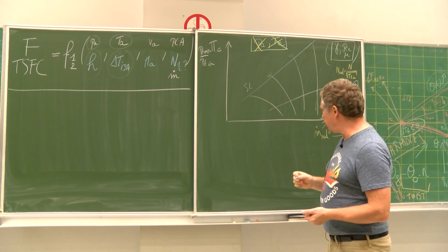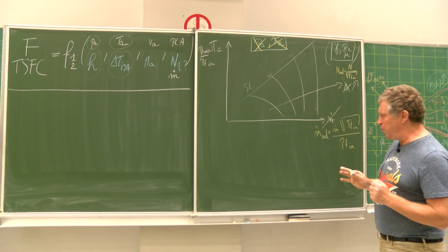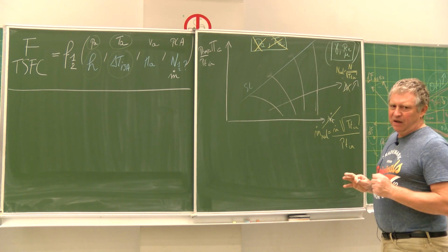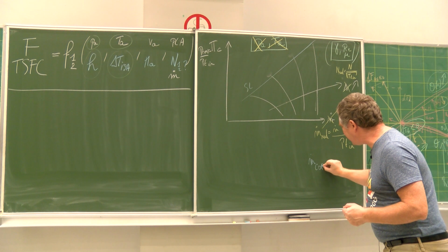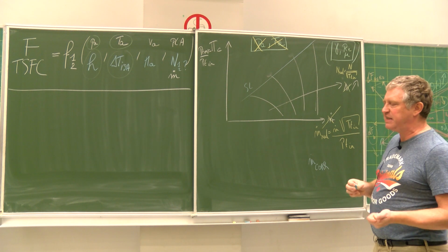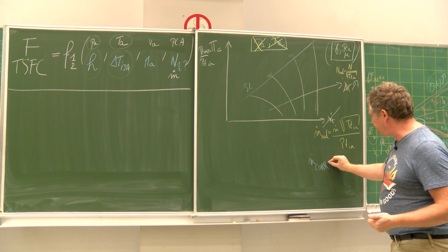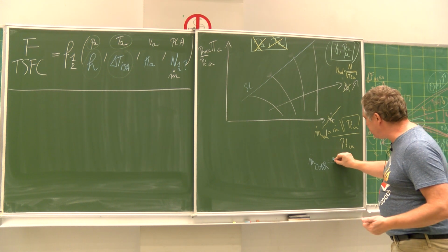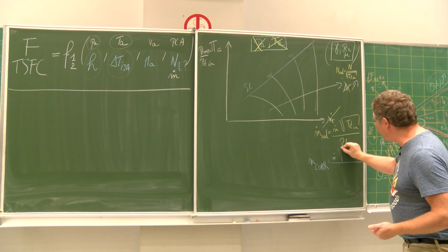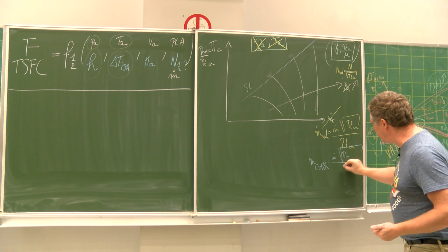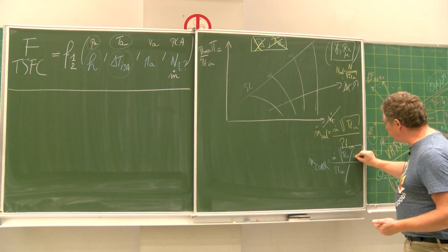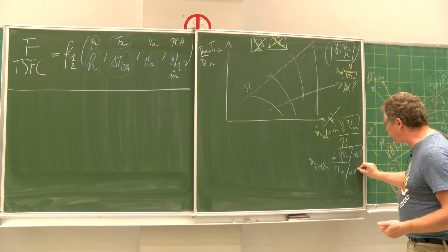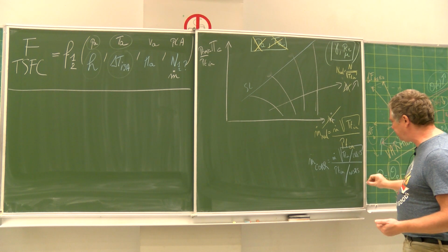I remind you also that we have introduced at a certain moment something else than the reduced parameter. This is what we have called the corrected, CORR, for example, as an acronym. That is not equal anymore to this one, but where we have introduced TT in and PT in, reduced by their standard values, 288.15 Kelvin, and here 101,325 Pascal.